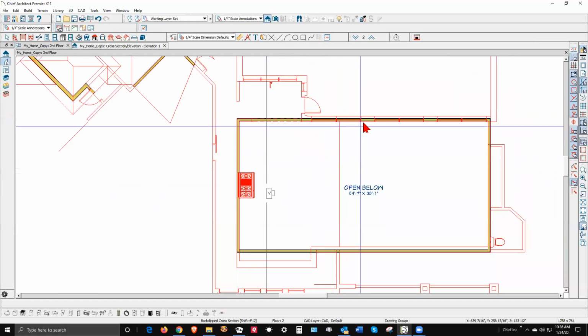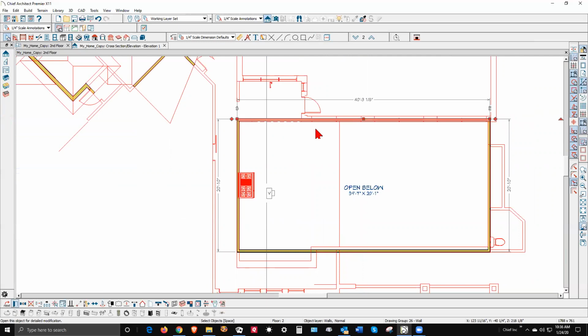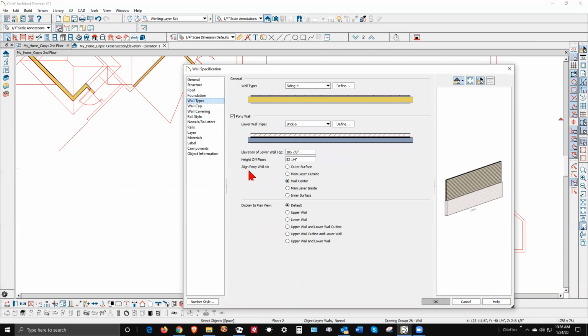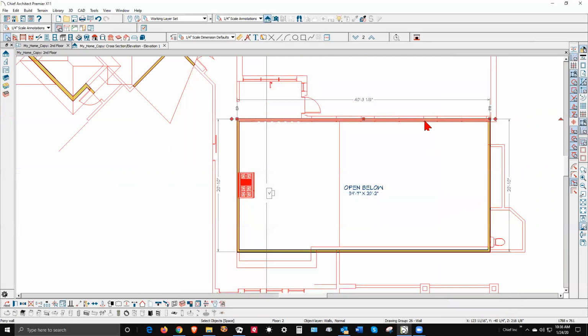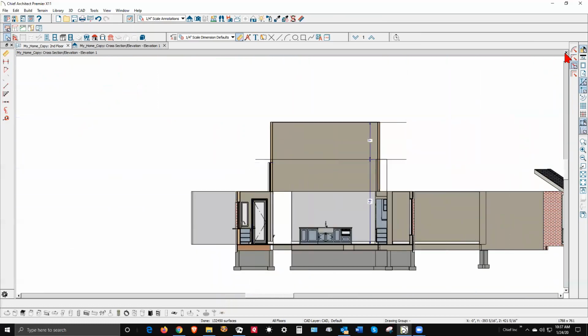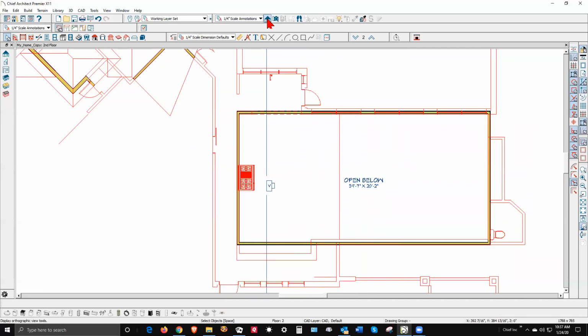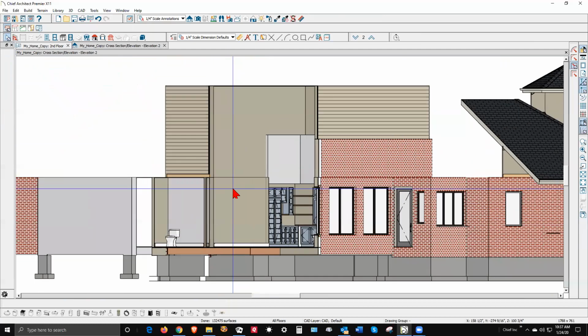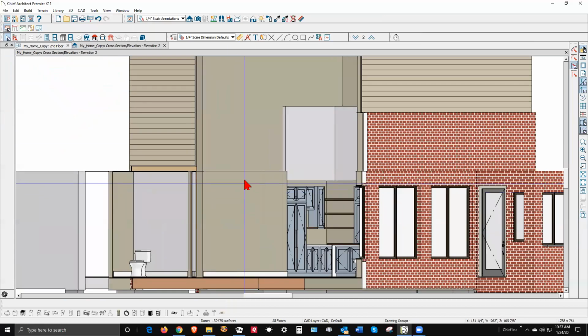And this upper pony wall, this one here, is not aligned properly. I want it aligned to the inside, which is not the default alignment. Let's see, it's wall types. Yeah, see here under align pony wall at inner surface. Now we go back to the elevation and see, yeah, that's lined up properly. Now I just have to get this right. I think what I'll do is an elevation camera at an angle here so I can see both walls. Well, it's not all that easy to check out. Okay, here's the line. Well, they do align. See, there's the break point.